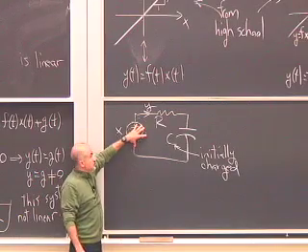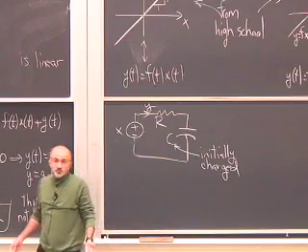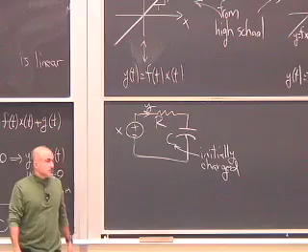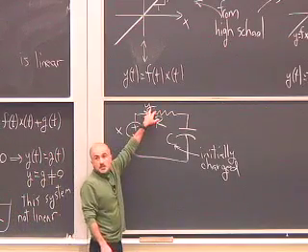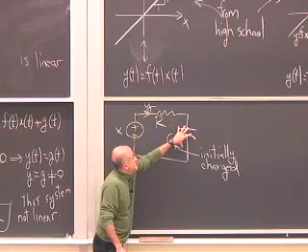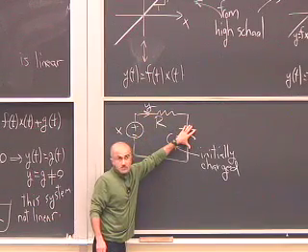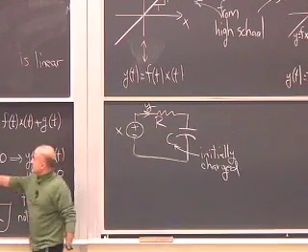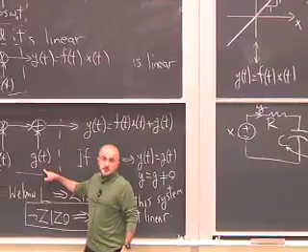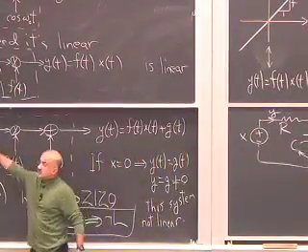Now, what if I have a situation where I have both the voltage source and the capacitor that's not charged? How do I figure out the total response? Well, that's where I apply superposition. So I can figure out the total current at any given time by zeroing out the charge in this, assuming that there's no charge on the capacitor. So the charge on the capacitor will produce a contribution to the current that's modeled by this G. And there's a contribution from the input coming from here.